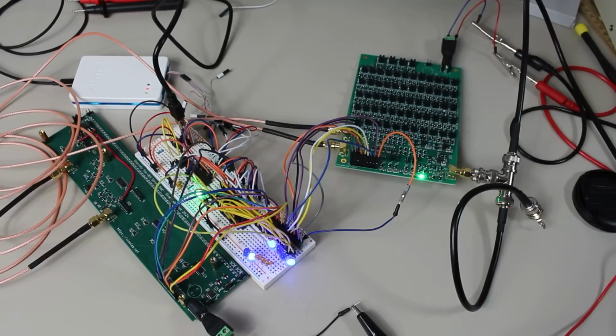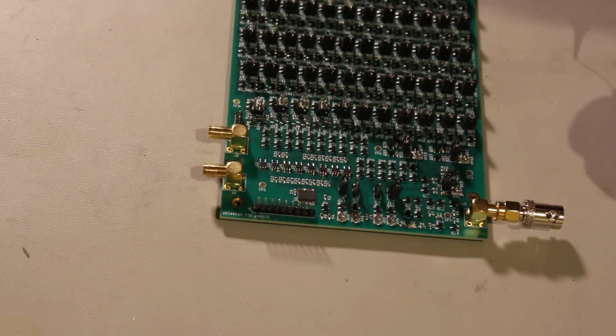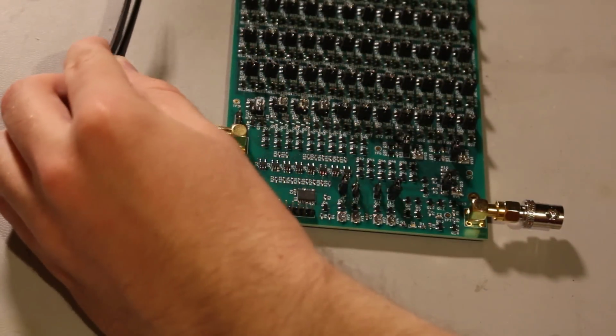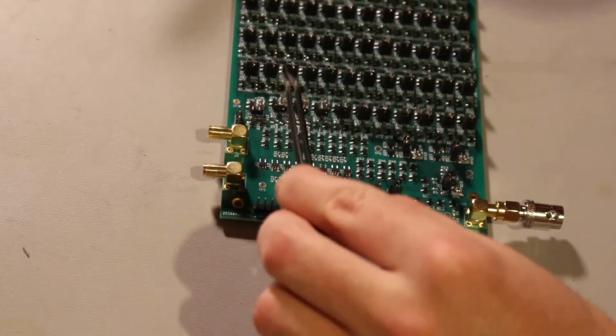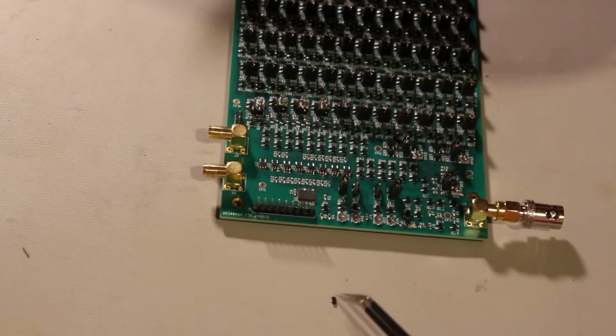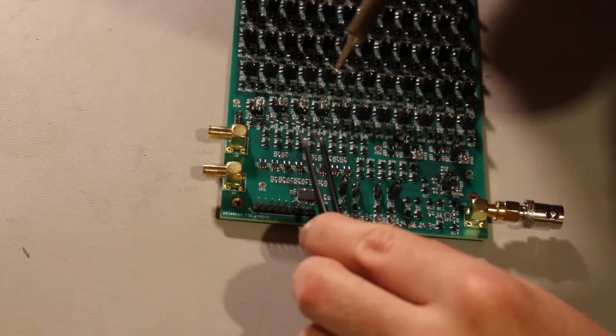For the entirety of this video, you may have been wondering why I was even bothering with this whole interpolator system when we could have just used a secondary string. Well, like I mentioned earlier, it removes the need for all of those resistors, switches, those two buffers, and potentially the output buffer as well. This sounds ridiculous when you look at the size of my board, but this is really just an educational demonstration for YouTube. In reality, this method only saves space if you are working on a semiconductor, where everything is much, much smaller. Remember, there are no monolithic buffer ICs or multiplexers in nice, neat packages on the semiconductor scale.